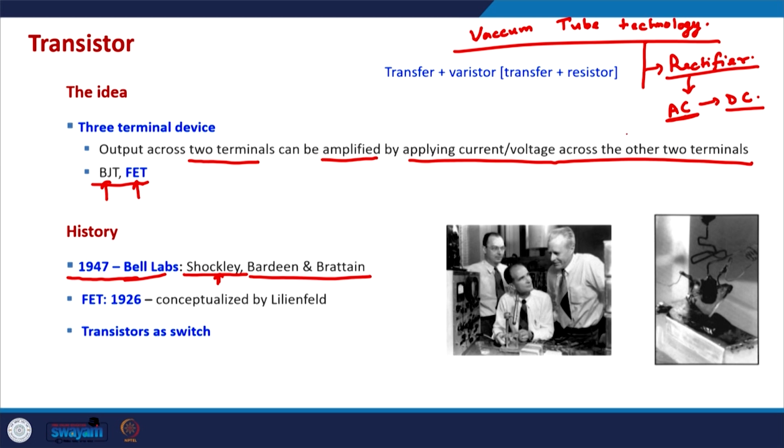Many countries, or at least the US, had a good network of AC distribution, but many electronic components needed DC current, and it was difficult and expensive to produce and send the DC form of current. And so that's why this conversion from AC to DC was quite crucial, and this was achieved using rectifiers.